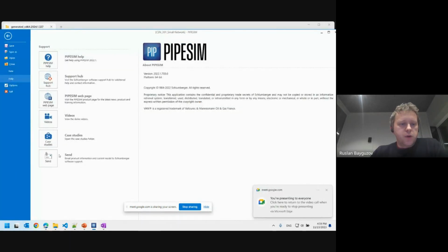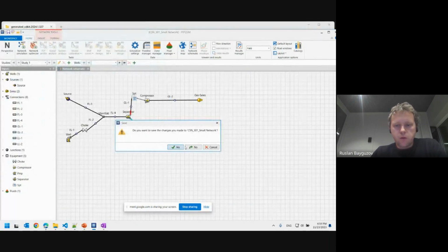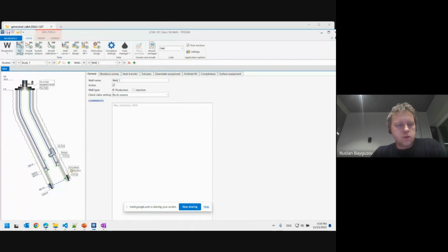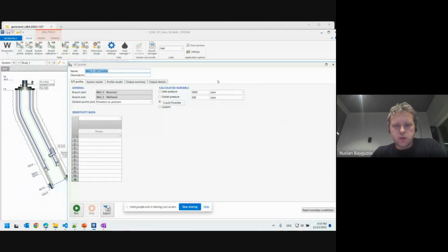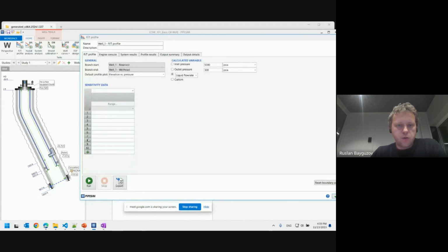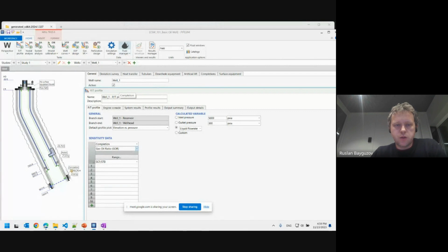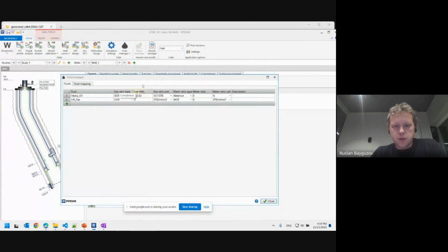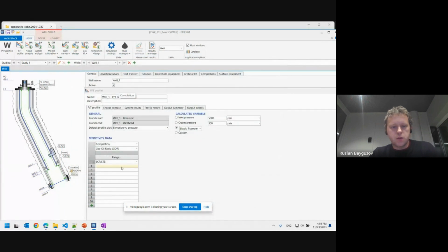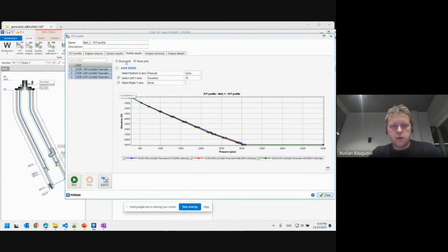Okay, so let's open any case study and make sure that I understand your question correctly. So let's take the oil well. I will use PT profile instead of the system analysis because it's easy to configure. Let me check. It works fine. Okay, I've got some results, and then I have a fluid. So in the completion, I can try to find what I can override. So for instance, the GOR. Let me have a look at what the fluid is. I think they use a heavy oil with GOR 200, and then I will use 200 and run the simulation. And I've got some results.